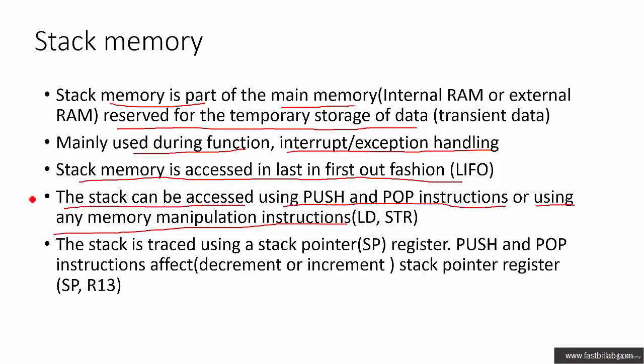stack memory. The stack is traced using the stack pointer register. So most processor architectures carry a special register called the stack pointer register. And that stack pointer register is used to trace the consumption of stack memory. When you use push and pop instructions, those instructions directly affect the stack pointer register. That means they can increment or decrement the stack pointer register values. In ARM Cortex-Mx processors, the register R13 is considered as SP, that is the stack pointer register.